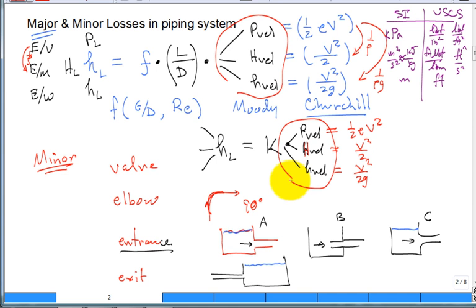See that? And so these are either energy per unit volume, energy per unit mass, or energy per unit weight. Either you talk about a pressure loss, or a head loss in energy per unit mass, or a head loss in energy per unit weight. Same units as I just put up there, in U.S. customary units, psi or foot squared per second squared or foot. So really, the coefficient that's new is just this loss coefficient.